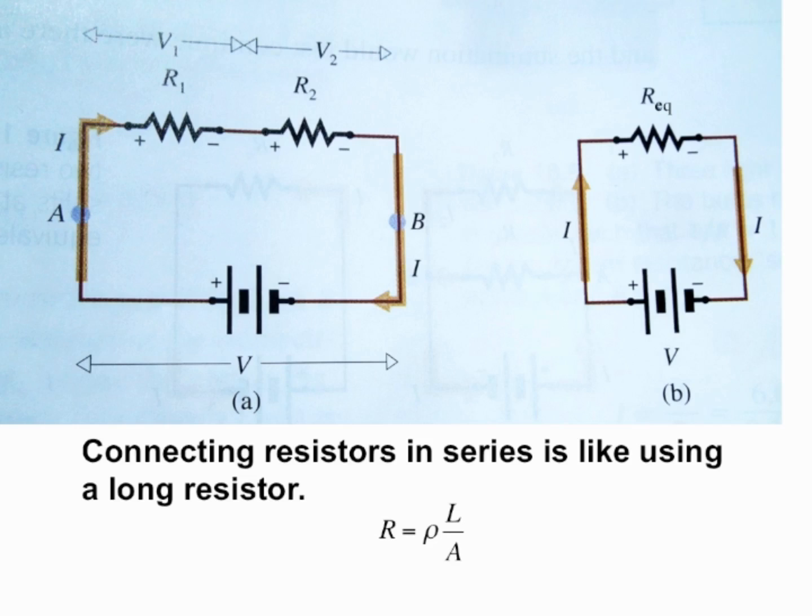And so we can talk about R_eq, or equivalent resistance, and that would be here in diagram B. The equivalent resistance would be just like having one long resistor. Obviously the lengths aren't drawn to scale here, but the behavior is the same. If you have two resistors in a row, it's like having a long one. And that's kind of how to make sense of why, when you're dealing with resistors, you really just add them up if they're wired in series. You add up the resistances of each resistor to get the total resistance.